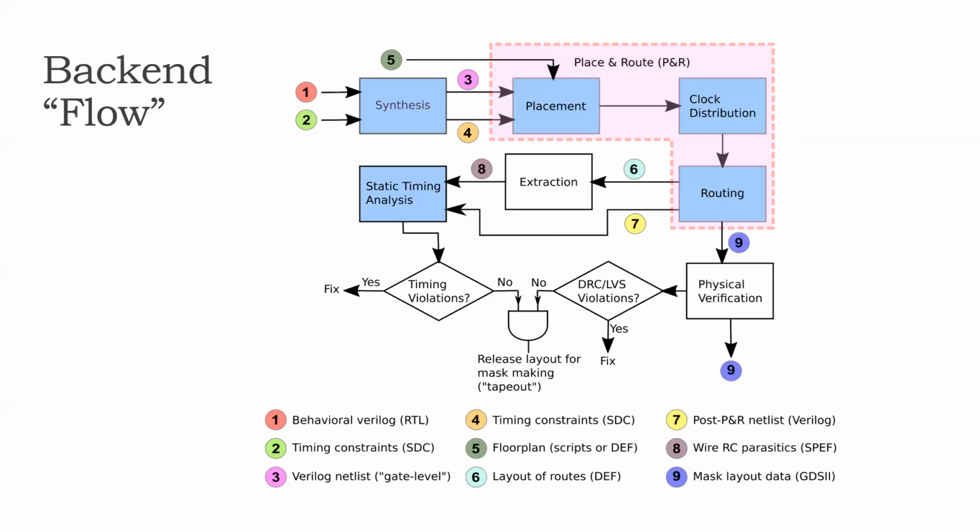Obviously, it cannot change the functionality of the circuit, but it can change the structure of the circuit by re-implementing combinational logic in other ways. And it may do that in order to optimize the results of the placement. During placement, if it finds that it's a better idea to implement some combinational logic in some other way than what the synthesis tool did, it will make that change.